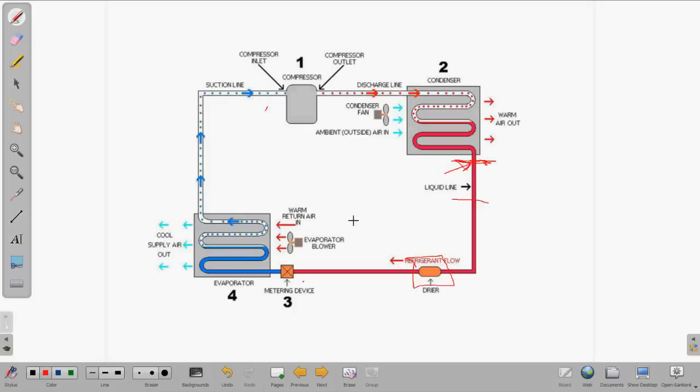And if you have a drop in temperature of more than 2 or 3 degrees, you know that somewhere between that metering device and the condenser coil there's a restriction or there's a kink in the line. And a lot of times you can only see several feet of the line set outdoors and several feet indoors, and it gets to be a challenge if it's buried under a slab or running through an attic, and then you have to go on the hunt.